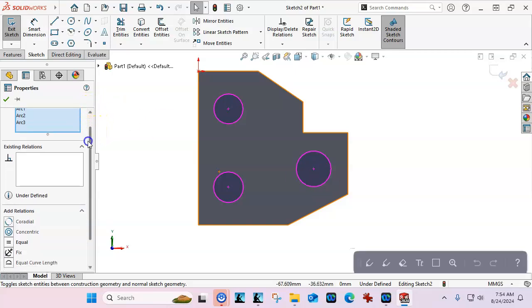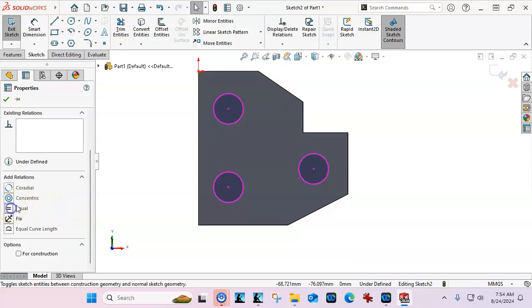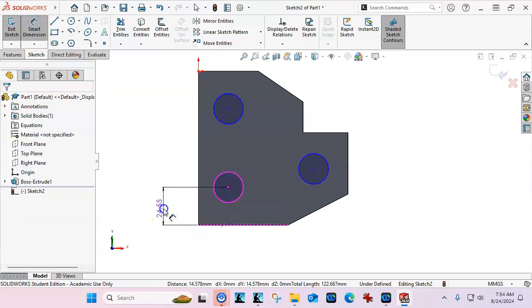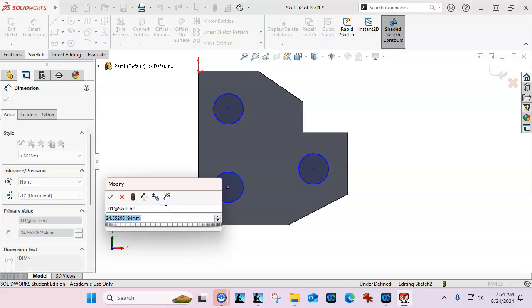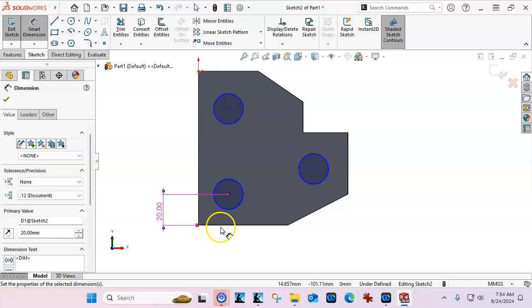All right, so since my context box disappeared, I'm going to come over to the properties, select the equal, go into the smart dimension, and we can put the two values, so 20. Now, because this has a linear component, a horizontal component, this wouldn't necessarily rotate.